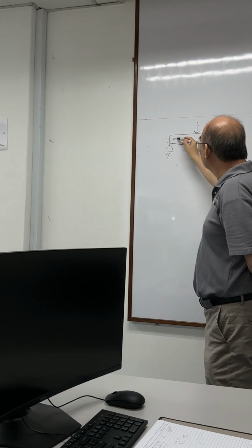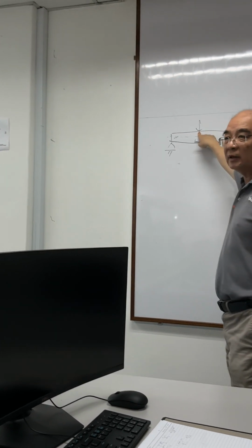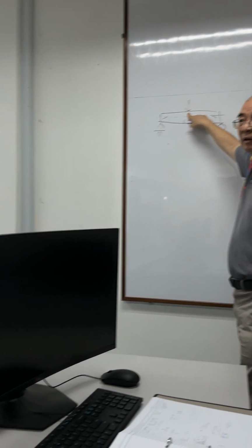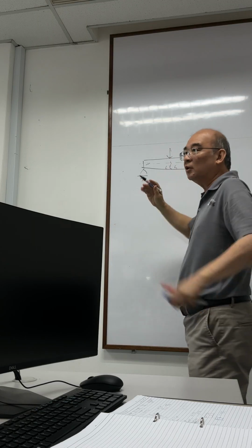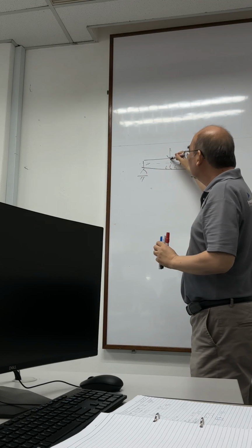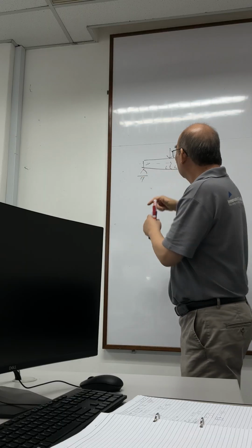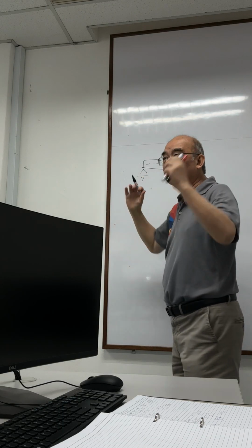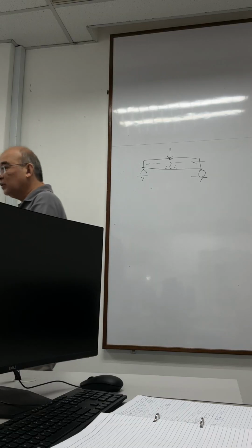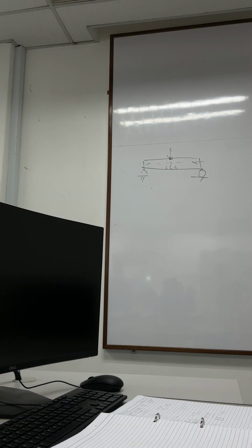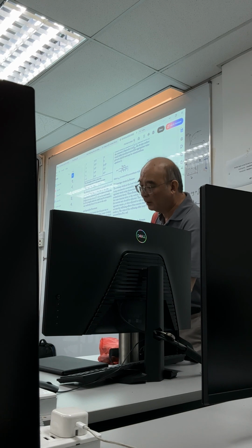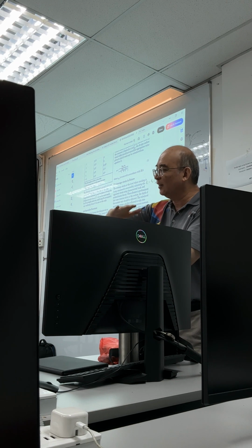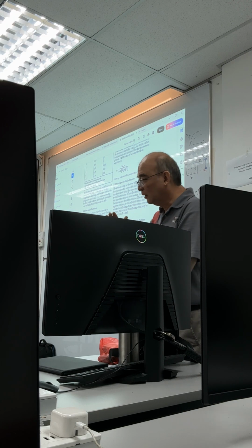Let's say this is the neutral axis. Are you saying that the cracks is happening here? Maybe. In fact, this crack will not propagate up to here because at the compression, you are going to have some crushing because of the compression crushing. Of course, the compression crush, of course, you see falling, but that is not crack. I mean, if you test it, you see cracks, right? But that is because